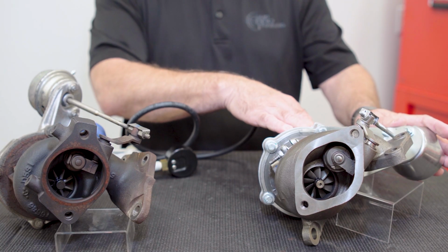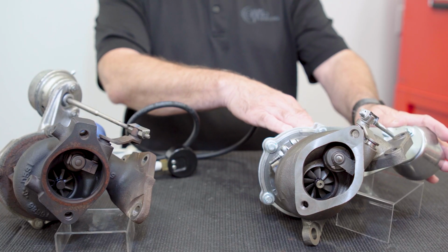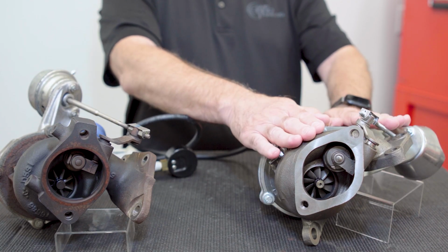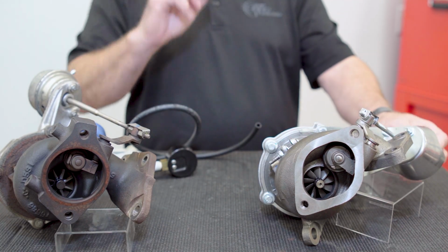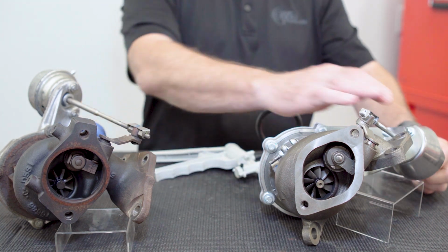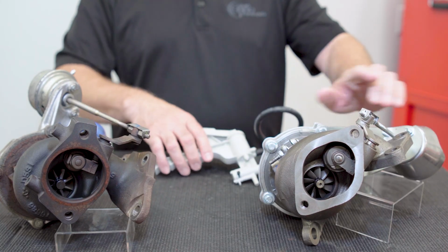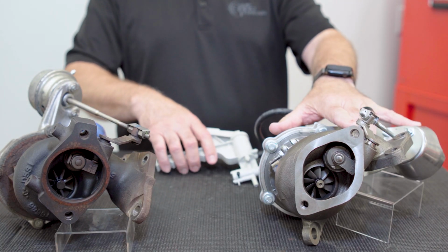But where does the pressure come from? Well, the pressure comes from boost. Remember, it's always on. So we always have even just a little bit of boost at idle. How does that work? Well, their system will apply pressure to the wastegate actuator, and as we apply it, you can see the wastegate actually move and open.